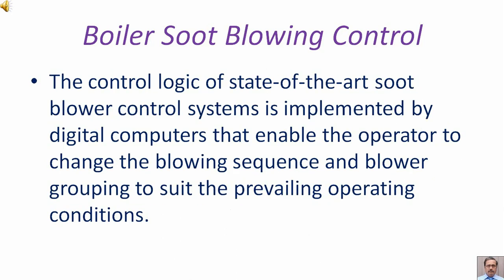The control logic of state-of-the-art soot blower control systems is implemented by digital computers that enable the operator to change the blowing sequence and blower grouping to suit the prevailing operating conditions.